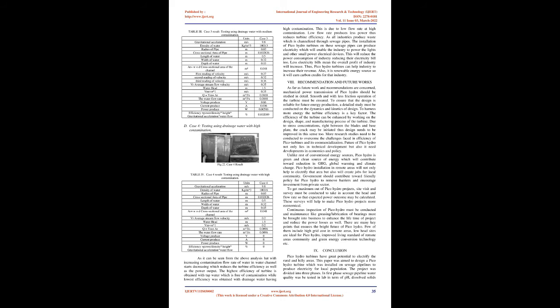6. Simulation results. The sewage water current in the pipeline hits the turbine with pressure, and the magnitude of this pressure decreases or increases depending on the location of the turbine within the pipeline. The hollow turbine design makes it easier for the solid impurities present in the sewage water to pass through, and the turbines begin to rotate under the influence of the flowing stream of high pressure water. When the turbine is in motion, the motion is transmitted through the rubber belt to rotate the generator.